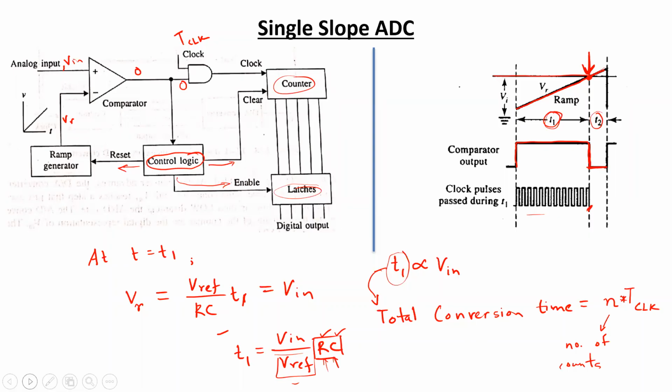No, the two are completely different. The operating principle of the two ADCs is completely different. That one uses a different type of register, the successive approximation register. The successive approximation register provides an output in terms of a binary bit sequence. That bit sequence has to be converted somehow. That's why the digital to analog converter is necessary over there.